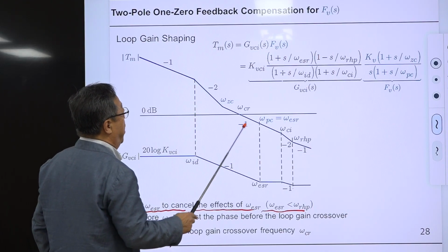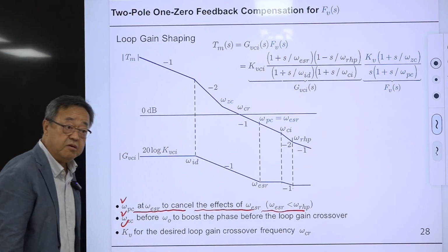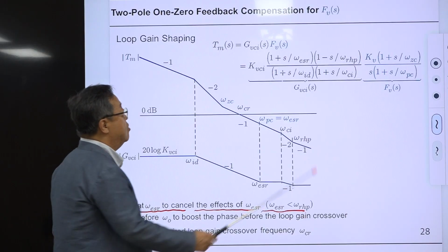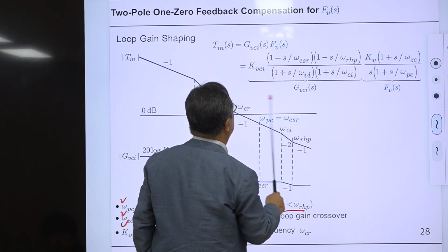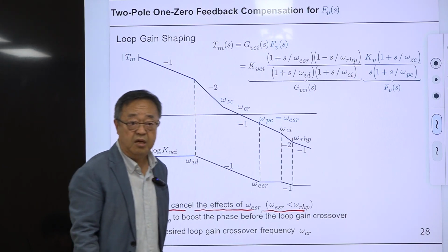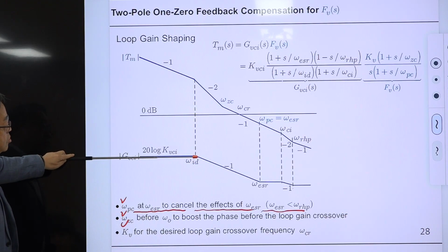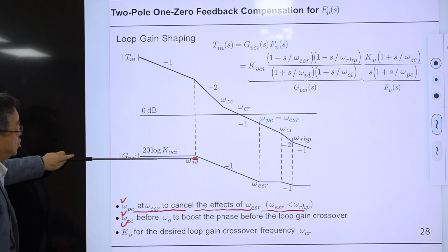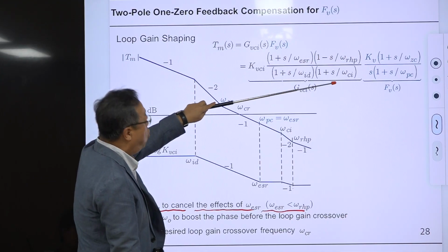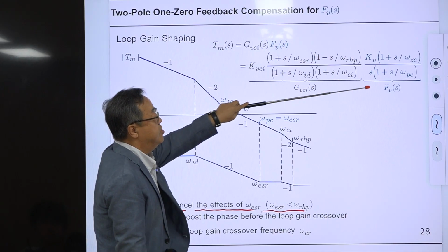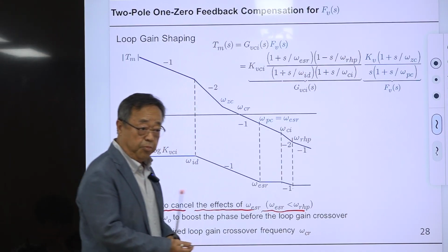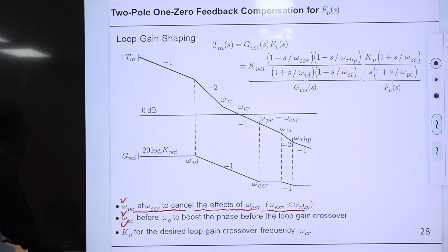Also, we discussed measuring this loop gain in the past. Previously we discussed how to measure this and this separately using PSIM, based on the time domain simulation computational method. This is just the reference. Using this, we wrote down this equation, and this is the required structure of voltage feedback compensation. So we start drawing the asymptotic plot from the low frequency.